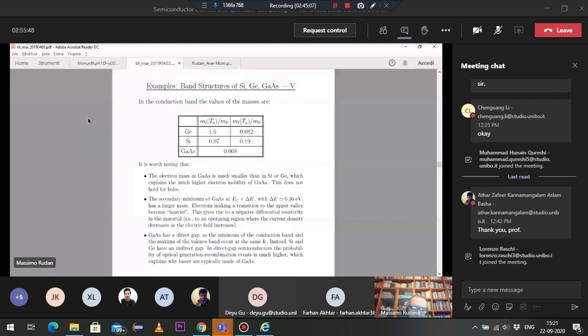This is somehow possible in the technology because this is not obvious, but if the material is subjected to a mechanical tension, the position of the valleys will change, and you may manage to displace the valleys in a way that the longitudinal valleys are not populated.